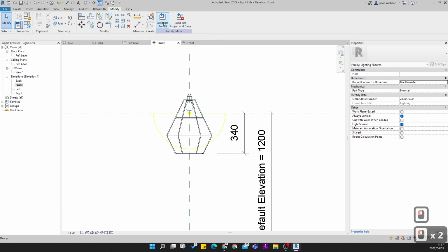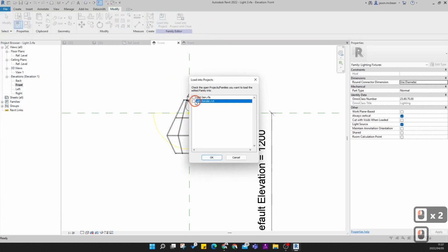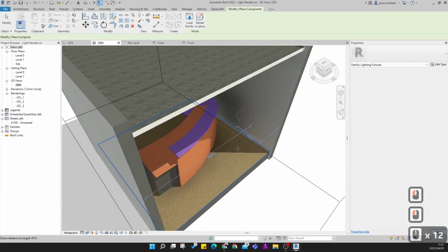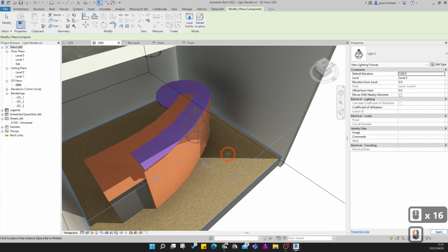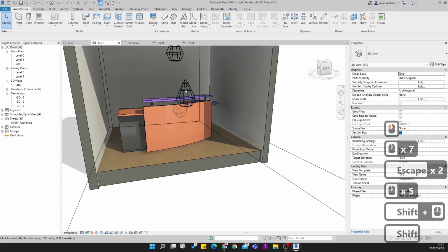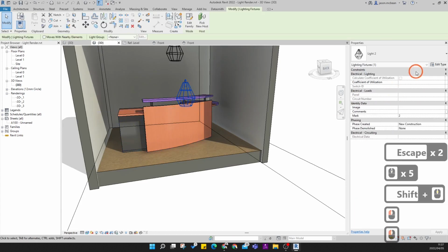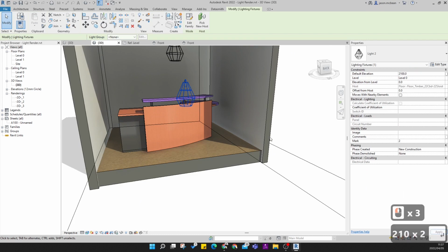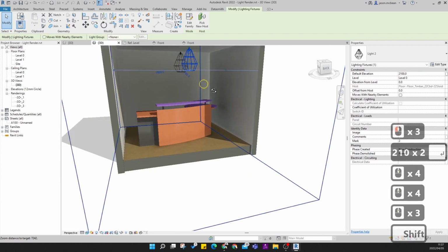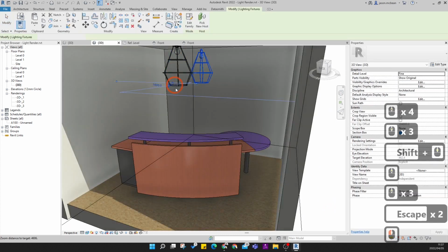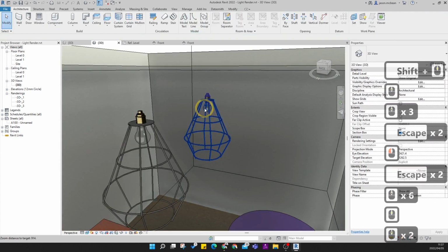And you're going to load this now into my 3D light rendering, so into the project file. Now, if you look, it's bringing in this light on the ground floor. Now I've got two light fittings in here. And remember, I need to change this. We've set this up here, to 100 from ground floor. So here I've got two different light luminaires. The one came in from AutoCAD, and you see the materials are slightly different.